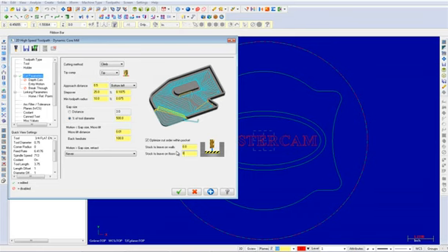Micro lifts are slight lifts that help clear chips and minimize excessive tool heating. Back feed rate controls the speed of the back feed movement of the tool. Retract controls retracts in the toolpath when making a non-cutting move within an area where the tool can be kept down or micro lifted. And finally, optimize cut order defines the cut order Mastercam applies to different cutting passes in a dynamic mill toolpath. Once the parameters have been adjusted, select Depth Cuts and disable it.